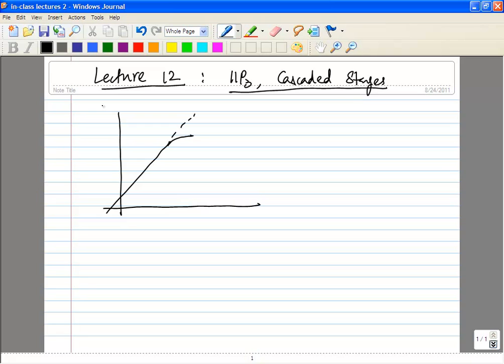So we know that because of some kind of nonlinearity, if you plot your output amplitude versus input amplitude in dB scale, you'll get some kind of compression, and the point where it falls by 1 dB is called the 1 dB compression point. Let's assume that's this. And we calculated it, right? We assumed a third order nonlinearity and we calculated your P1dB to be root of